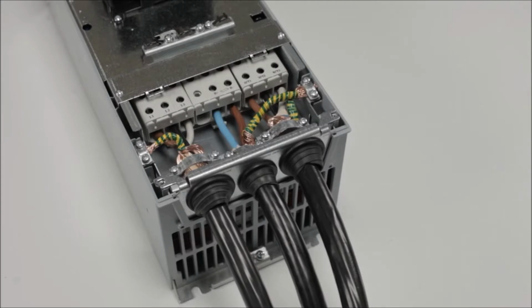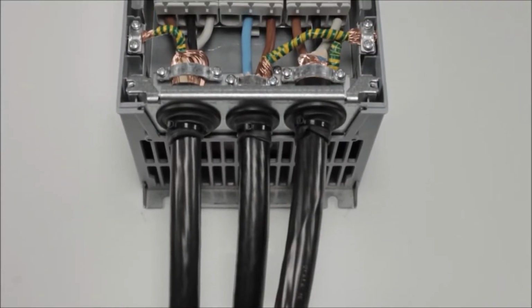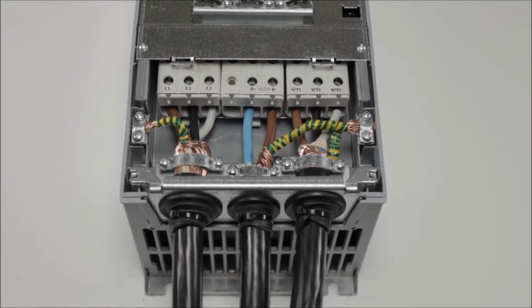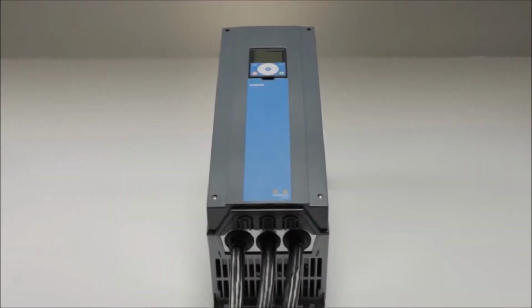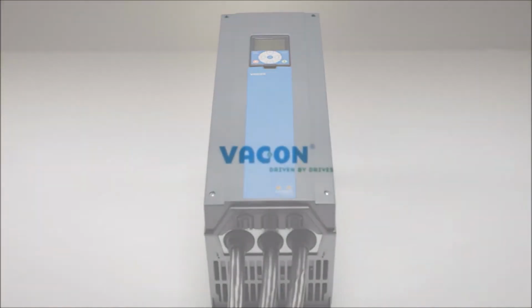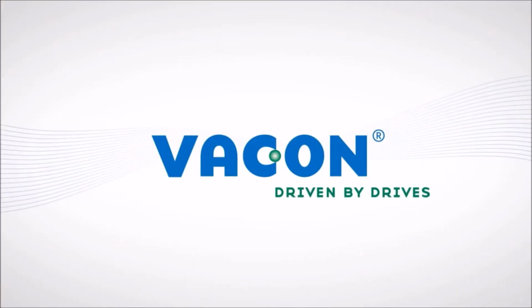Connect the supply, brake, and motor cable conductors to the correct terminals, which can be identified by the labels on the sockets: L1, L2, and L3 for the supply cable, and U, V, and W for the motor cable. If all has gone according to plan, your drive's power cables should now be connected and ready for action.